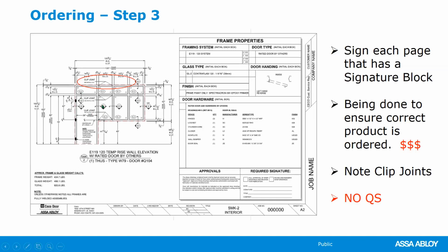You will have different cross sections and details as part of the shop drawing, showing all the details of the preparations that are going to be provided for hardware. If you notice here, the most common delivery is knockdown. In other words, each one of these pieces would come individually, and then you'd use the clip system to assemble it in the field. Another option is to have certain portions of it welded, and that's what this shows.